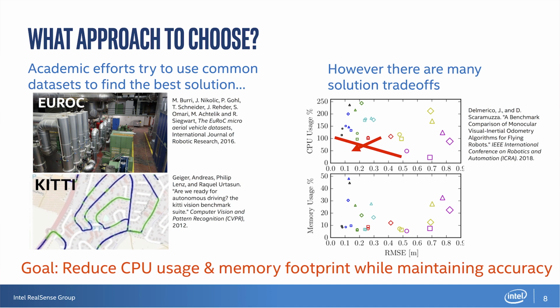And in this slide, I would like to talk about benchmarking, which is one important aspect due to the variety of different approaches. I'm highlighting here 2 different data sets. There are many more. One of them is EuRoC for drones, has stereo pair, IMU, and external measurements to obtain ground truth and assess the accuracy of the algorithm. The other one is KITTI, aimed at autonomous driving applications. Was recorded in the downtown of Karlsruhe in Germany, and that one as well has odometry from the car and uses GPS as ground truth.